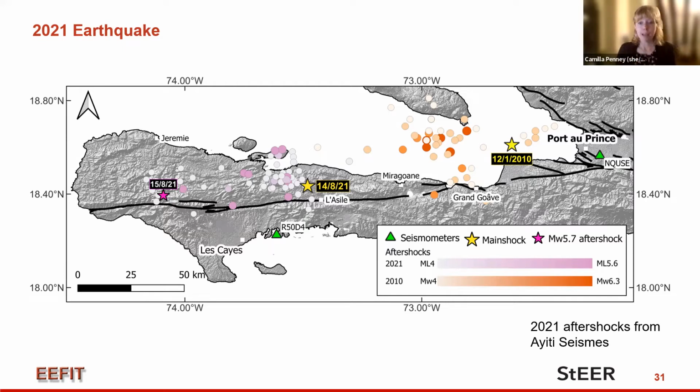However, it transpired again, based on the seismology, that in fact this was an oblique fault rupture, and it had occurred on a fault which dipped to the north, which is the opposite sense to dip that had been mapped on this major fault prior to the earthquake occurring.